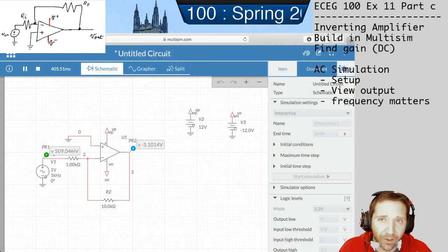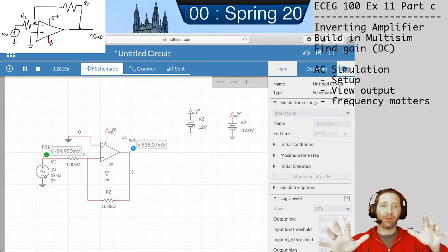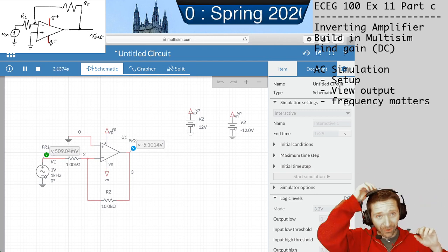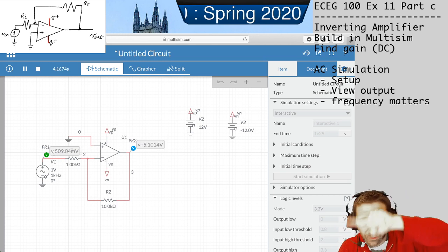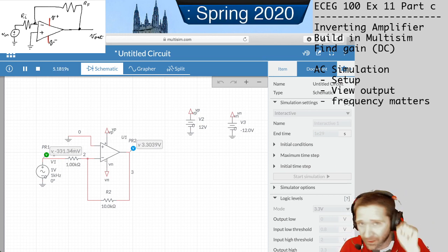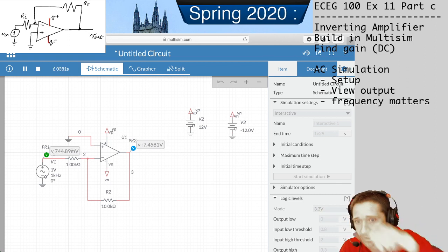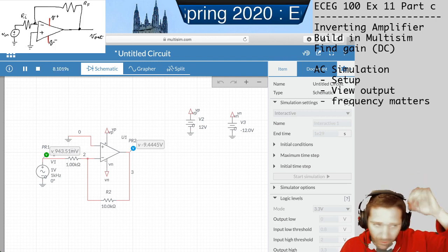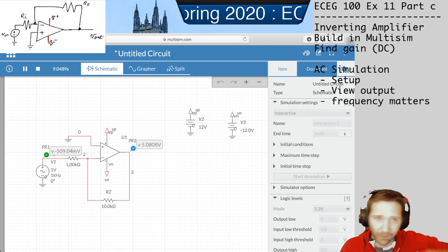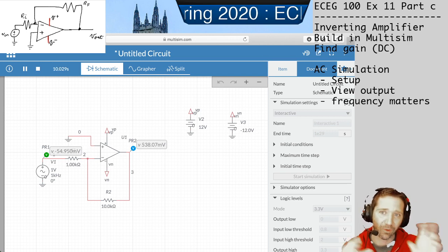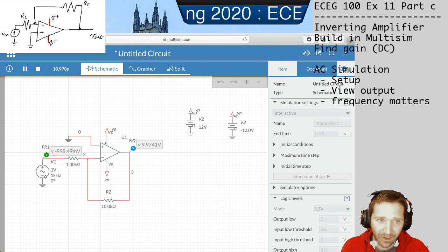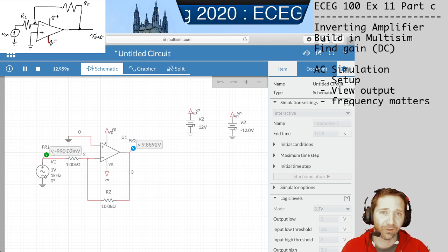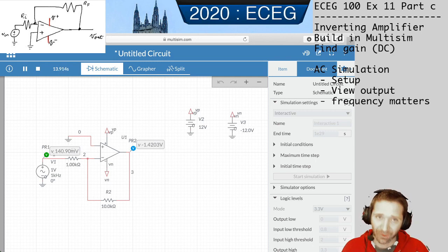All right, it's running. Now, I think a lot of you had this happening: the numbers are doing this. Please don't screenshot that. They're going crazy. The numbers are all over the place because you have a sine wave going up and down, and every once in a while the simulator picks the value and displays it. That's hard to do because it's jumping between 0, up to 1 volt, down to 0, down to -1 volt, and back. It keeps oscillating, and we can't pick the values consistently. Likewise, our output is jumping all over the place. So your engineering intuition should have said this is not the right way to do that, and you are correct.